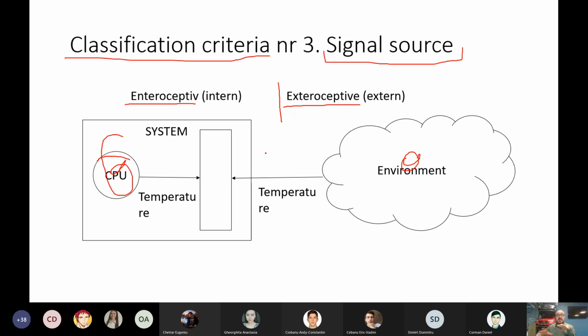value. And in this case, when you look at the datasheet of the sensor, you will see the purpose of the sensor, because when measuring the outside temperature, you will have a special construction of the sensor to gather a bigger area in order to have the average value of the temperature. In case of the internal temperature, we can have some material, just touch it and measure very precisely. Outside is a different problem.